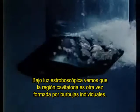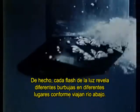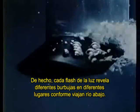We have been looking at the cavitation under incandescent lighting. Under stroboscopic lighting, we see that the cavitating region is again made up of individual bubbles. The apparent dancing is only a consequence of the strobe lighting. Actually, each flash of the strobe reveals different bubbles in different locations as they travel downstream.